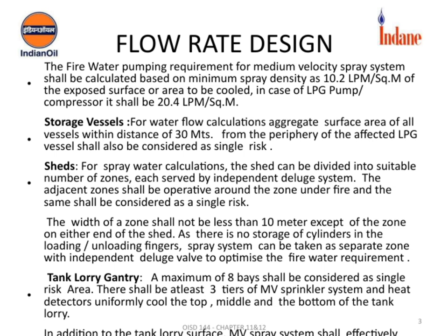Now, considering the tank lorry gantry, we consider up to 8 bays as a single risk area. To ensure effective coverage, at least 3 tiers of medium-velocity sprinklers and heat detectors are installed to cool the top, middle, and bottom sections of the tank lorry. Moreover, the spray system must also effectively cover the tires, manifold, and dish ends of tank lorries of various sizes, ensuring comprehensive protection.